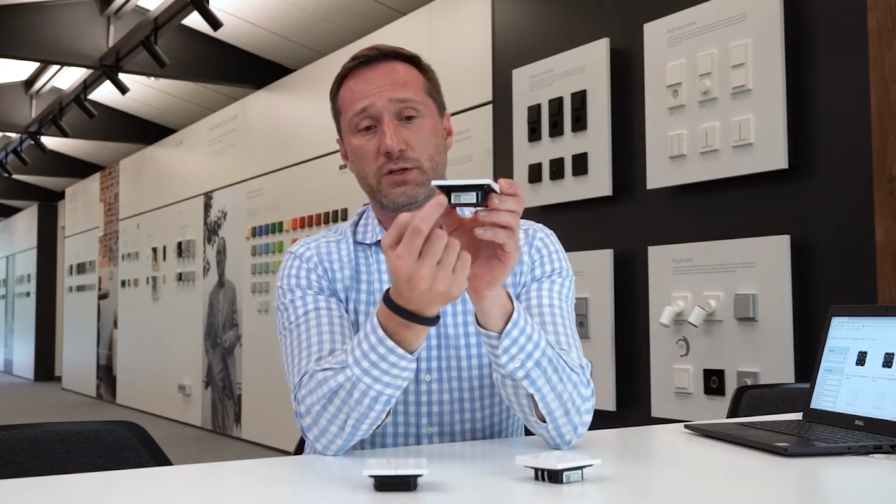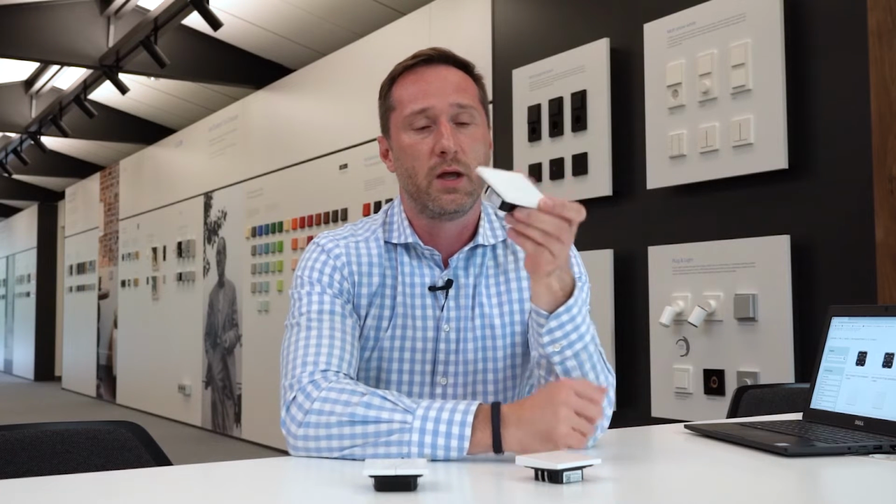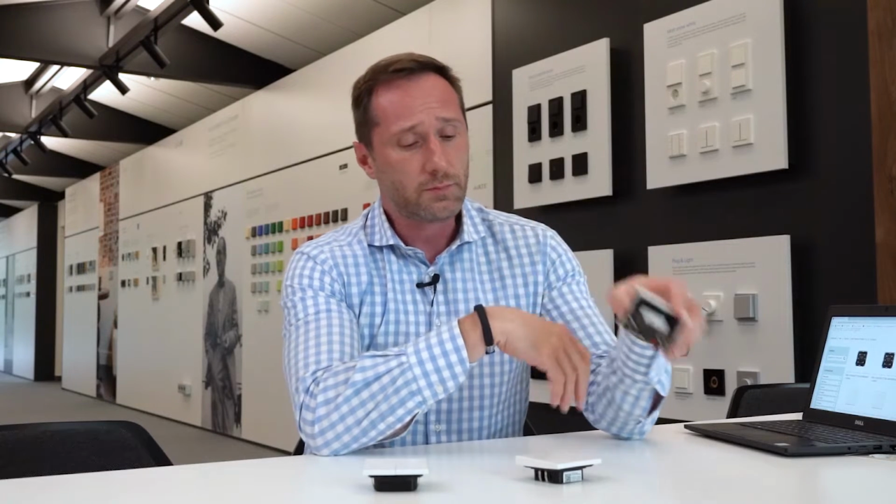So normally everybody would know how to operate this push button intuitively: you can press on the bottom, and of course also on the top to switch on the light, to dim it up and down, or to control the blinds up and down. Additionally, you can see on the device the so-called KNX Secure Device Certificate, which is needed to be uploaded in the ETS to use the KNX Data Secure functionality. And of course on the back you have the KNX terminal.